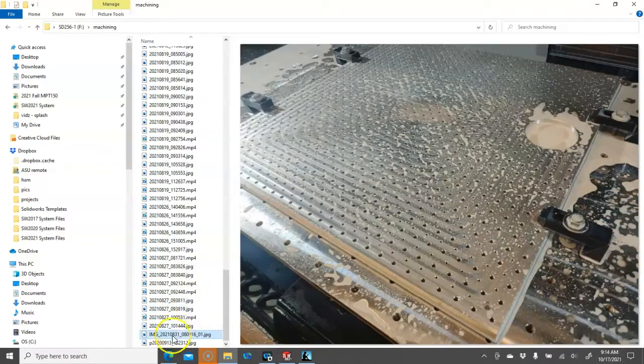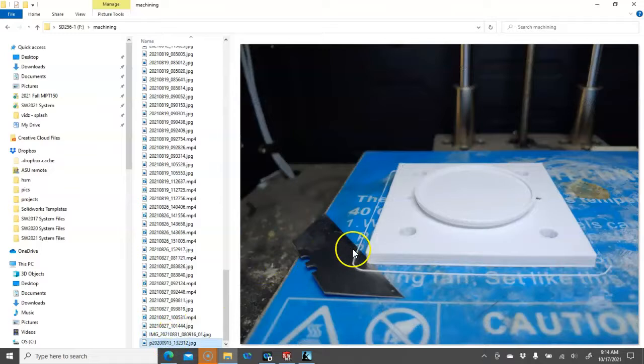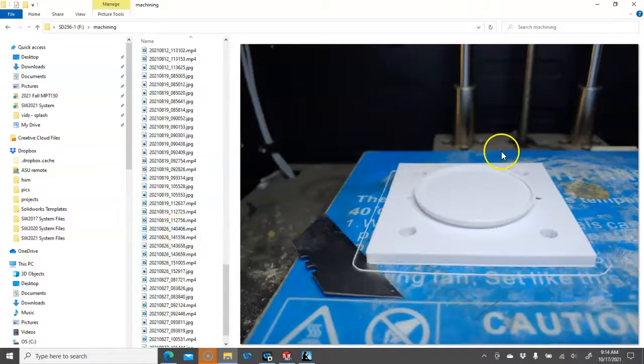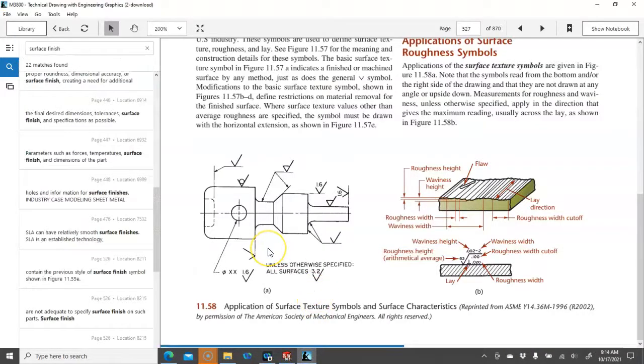And then a 3D print. So the 3D print, again, we're going to see the same types of things with the plastics. Being a pliable material, the surface finish of the 3D print is based on the resolution of the part, and so you kind of get what you get. There are things that you can do with the 3D prints and the finishing, but for the most part, we're not going to have the same level of control.